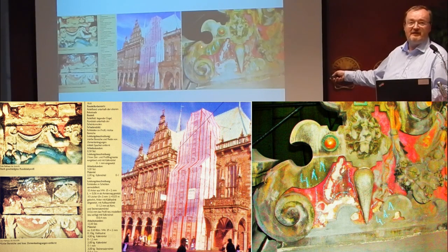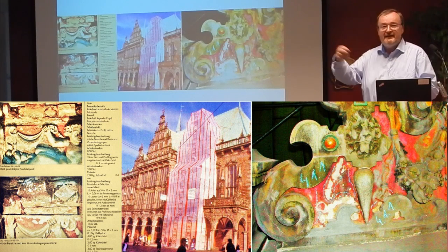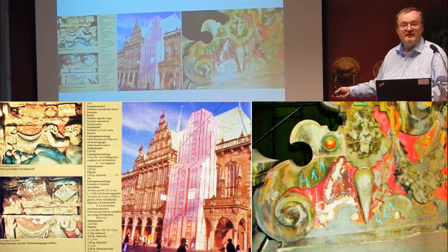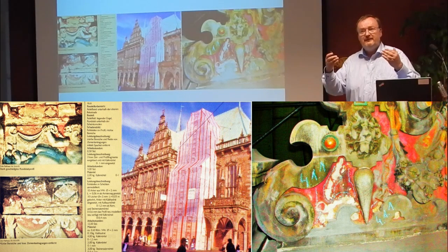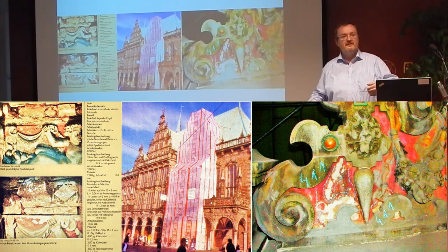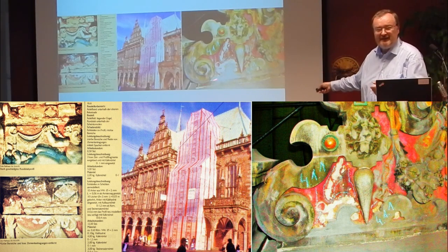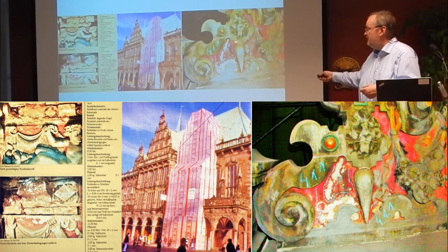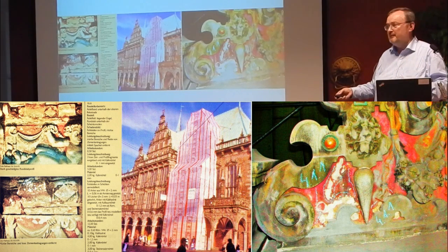You can see it by chalk. We go there and we decide every part. For example, here we decide to have a little layer of color, of paint. And for example, here not. So to discuss a patina problem, we said, if we are standing in front of the facade, what will hinder understanding the architecture, like big white parts in the colored facade? We will have a retouch. And the other parts, which are only little damage, we leave. We can save the money.